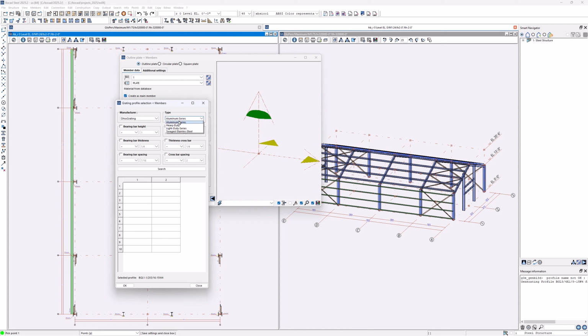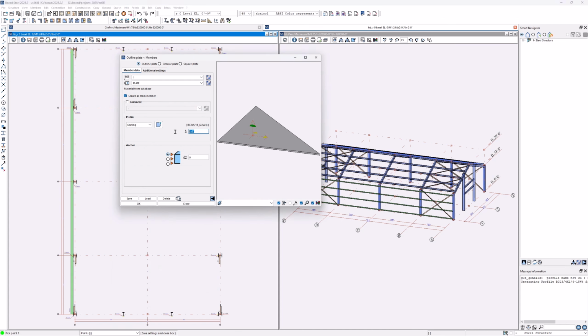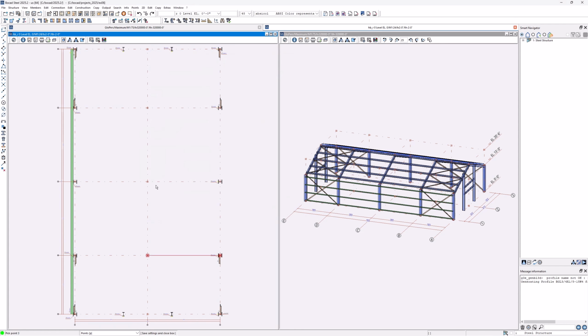Each supplier might take a second or two to load, since the types can vary from one supplier to the next. Just choose one of the types. We can filter on specific properties, then search in the catalog what's available. Just choose the grating we need. Confirm. No expansion in this case, maybe. OK, 1, 2, 3 for that grating.